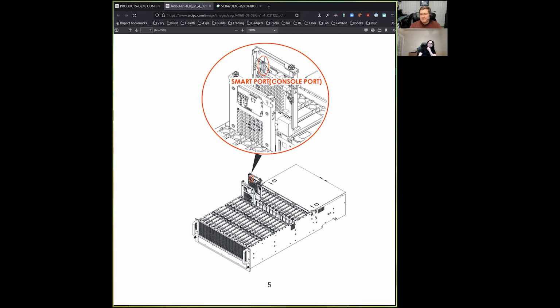and so that could be another one of those advantages, a good benefit here of having those 3 backplanes in there, is now you've kind of got your system split up across essentially 3 controller cards, or 6 if you include the primaries plus secondaries. So you're kind of expanding the size of that pipe as well. You're not just worried about controller failure and redundancy in that case, but you can actually push more data through the system by doing that as well.